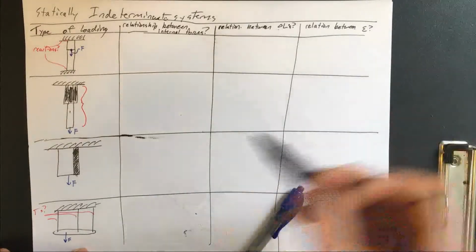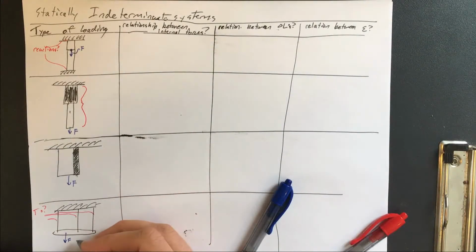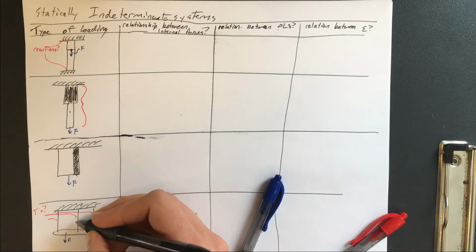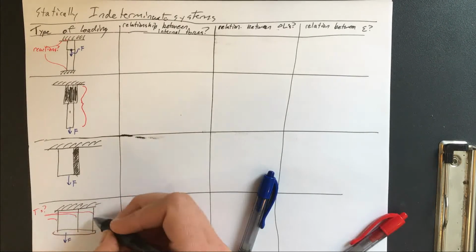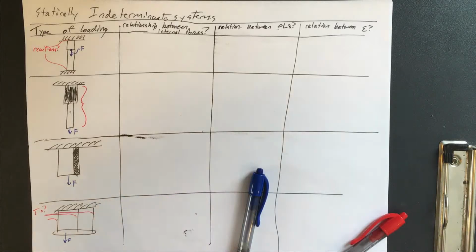But if we know that maybe this beam on the bottom is rigid and it can sort of translate and rotate, then that gives us kinematic constraints, and information about how stresses and strains are related in the wires can give us that last equation to resolve the unknowns.